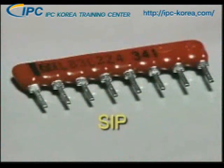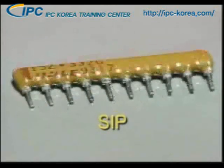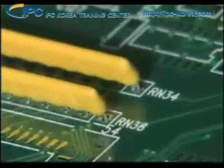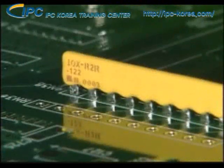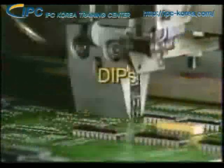SIPs consist of a single row of leads and are often resistor networks or diode arrays. The reference designator for a particular SIP is based on the function. For example, resistor networks will usually use the letters RN. In many cases, a dot or number will indicate pin 1 for orientation. DIPs are the most common through-hole IC.